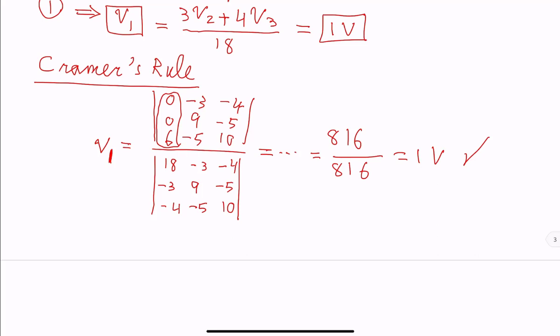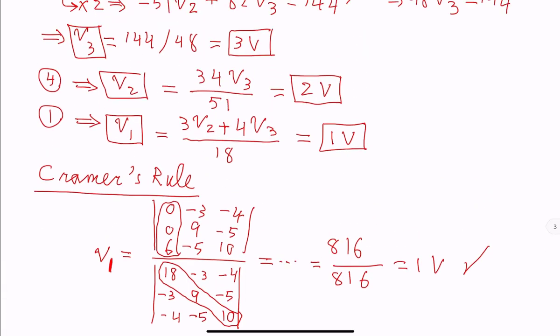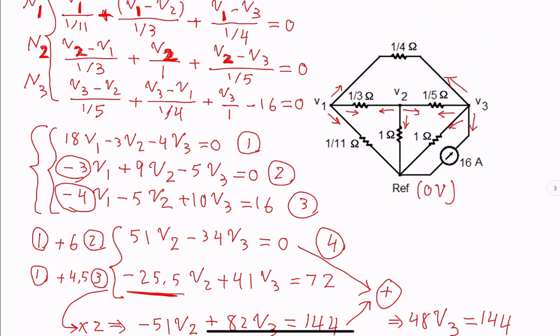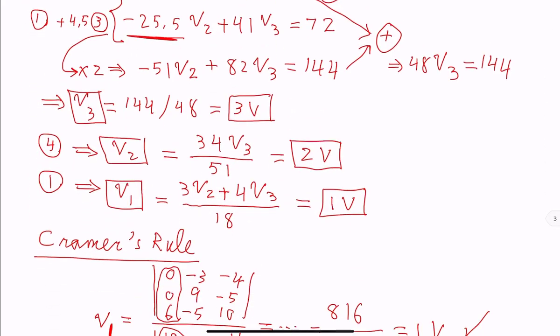Some books emphasize the form of this matrix. We see we have positive numbers on the main diagonal, negative numbers off diagonal, and also the matrix is symmetric. Those are the properties that we see because in this circuit we only have current sources and resistors. With current sources and resistors or conductors, that will happen, but if we add dependent sources or other types of elements or voltage sources, we will lose that. So it's not really that important.